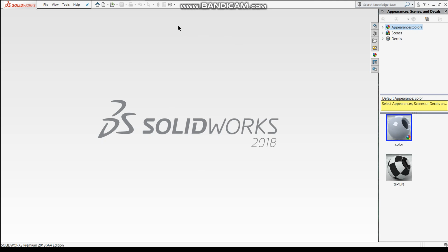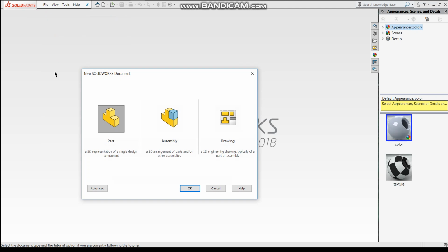If you have already installed SolidWorks, and if not, you can watch videos on YouTube on how to download SolidWorks, then we can start our video. We can start learning different things. When you start SolidWorks, you will see a background like this, and there are three main actions here. One is you go to File, Create New, and one is Part.